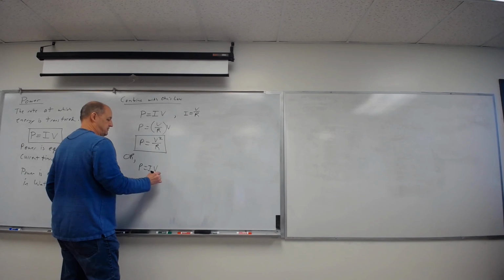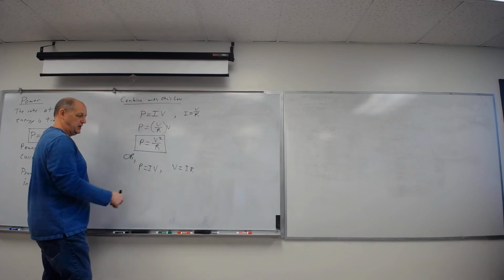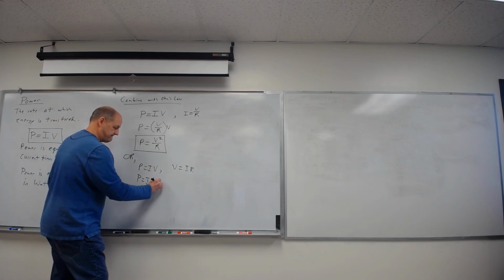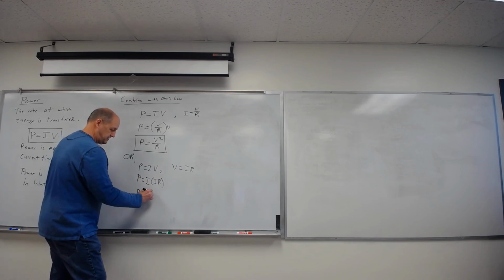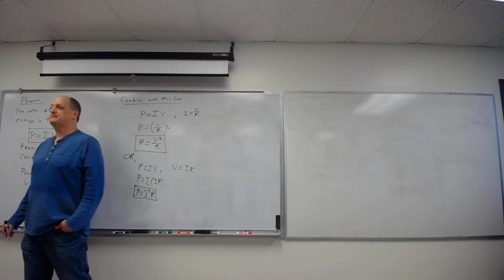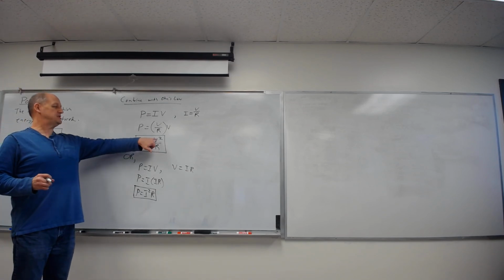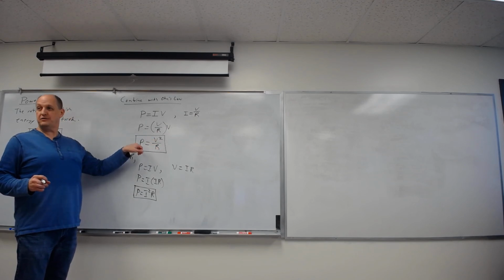Or power equals current times voltage, and I know voltage equals current times resistance, right? These are just two expressions of Ohm's law. I can plug this in, and I end up with current squared times resistance. So that means if I have my resistor in there, it's a 1/4 watt resistor, I can double check and make sure, if my voltage gets too high above that resistance, my power will go over 1/4 watt, 0.25 watts. Those resistors I passed you, and it will get too hot, and it will start to smolder and get hot and uncomfortable.